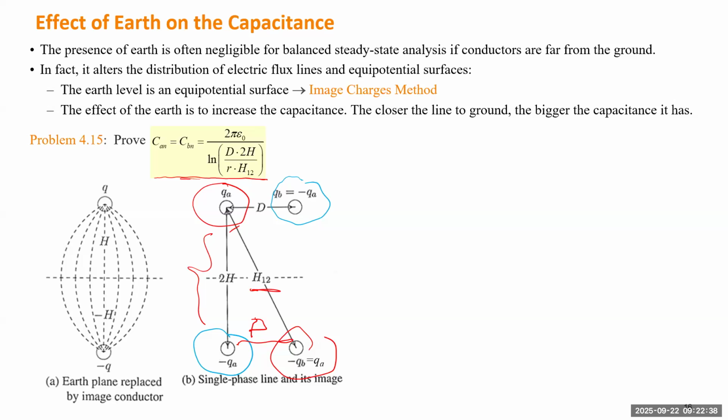So you see, this formula is very similar to the formula we know if this part is 1, right? So our original formula to calculate capacitance per conductor will be 2 pi epsilon 0 divided by log, then there's a fraction, capital D by lowercase r.